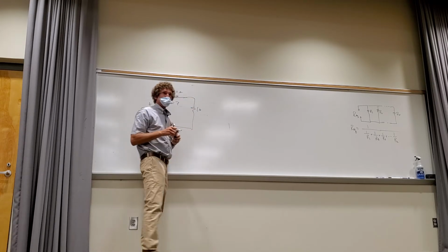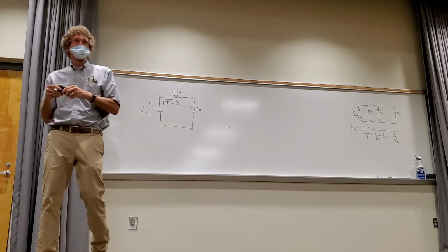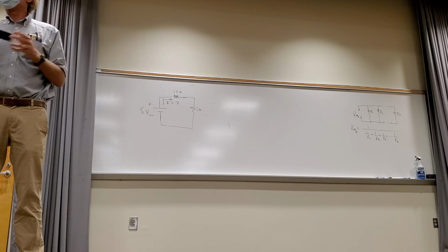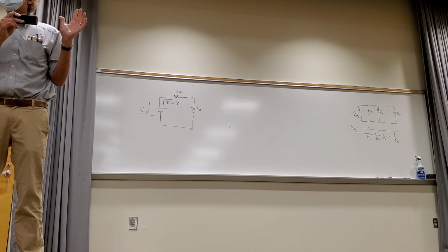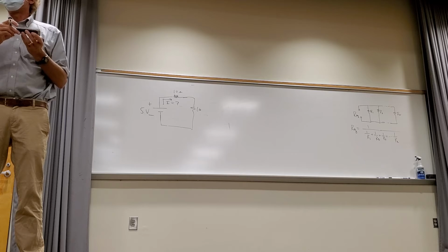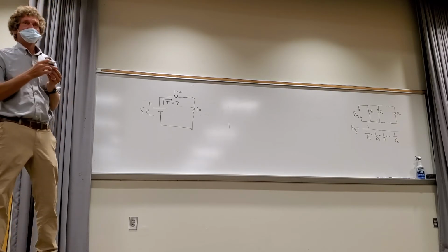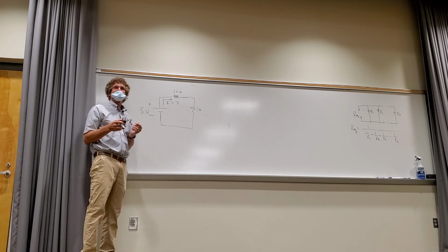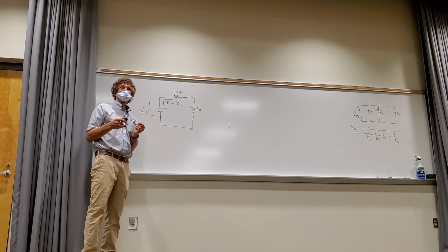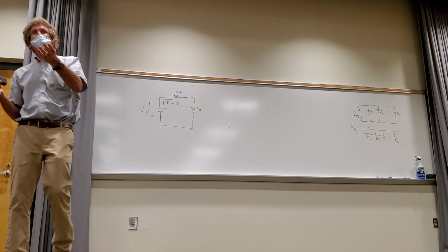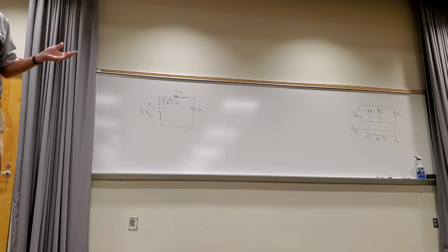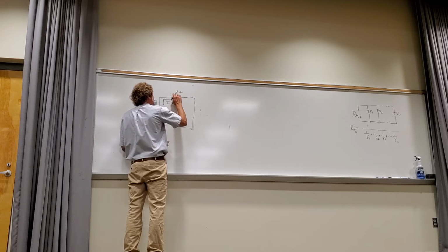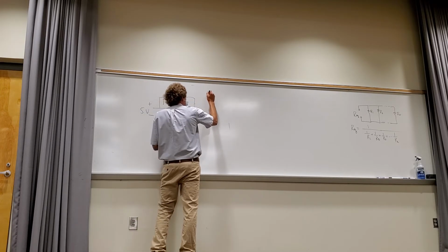All right? We don't need to go Kirchhoff. I never try to use a bigger tool than I need to drive a nail in or to solve this kind of stuff. I try to keep it as simple as possible. Don't use anything you don't need to. So now finally, what's the current? What do I do with these last 2, anybody? Now I'm boring, you're ready to start throwing tomatoes at me. But what do I do? Add them up, and what are they? Just 20 ohms, right? So make that 20, and now what's that current going to be?